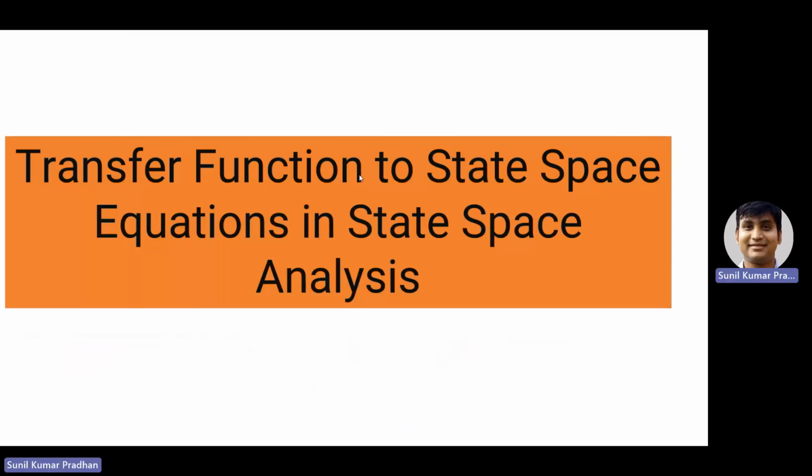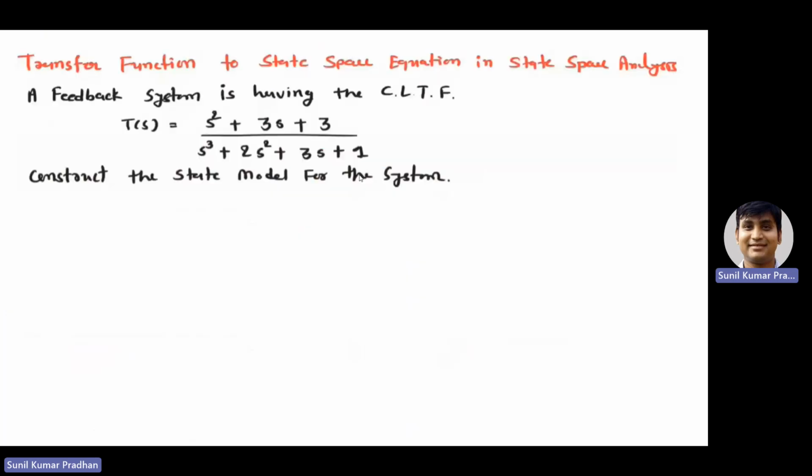Now we'll discuss transfer function to state space equation in state space analysis. Let's consider the question like this. A feedback system is having closed loop transfer function, your CLTF, which is equal to s square plus 3s plus 3 divided by s cube plus 2s square plus 3s plus 1. Now construct the state model for this system.